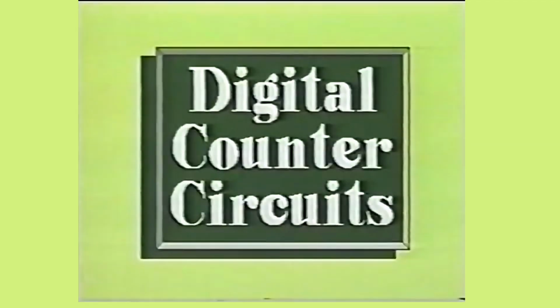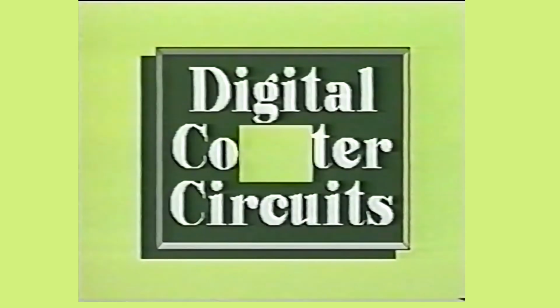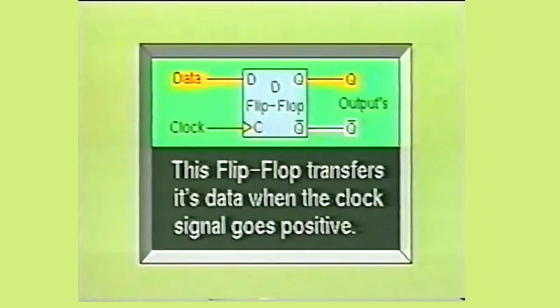Now we will examine various counter circuits used in digital equipment. Because of their versatility, counters are used in many applications, such as arithmetic circuits, code converters, analog to digital converters, and waveform generators. This part of the video will concentrate on basic counter circuits. The primary function of all counter divider circuits is performed by the flip-flop, which, as you have seen, changes state when the clock pulse does a positive or negative going transition.